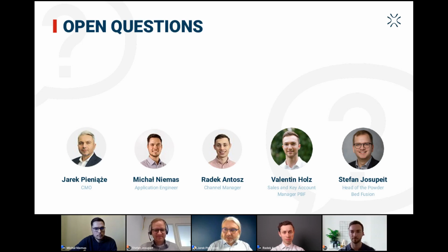Okay, thank you. And Kathum is asking what is the best adhesive you recommend to stick printed parts? I think that it really depends on the material that you're using, but many of our customers are good enough with cyanoacrylic glue, gluing the parts. I have had many people, hobbyists and modelers, who were using not glue, but snap fit design in order to connect parts together. I don't know how it looks in your country, but in our country, it's called super glue, and it works perfectly. Basically, you can try cyanoacrylate, epoxy, or even neoprene glue. So you can choose the best way.